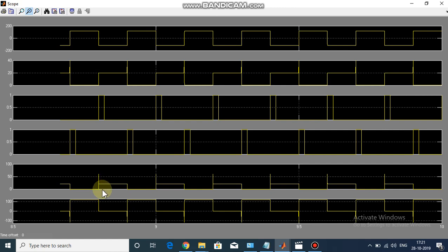So this current plus the around 120 volts appearing due to the capacitor going to the other resistor, those two node currents get added up, and that is why there is this spike. Once the capacitor gets charged up, the spike goes away, and then there is just the normal V divided by R current that we'll generally be observing through the capacitor.